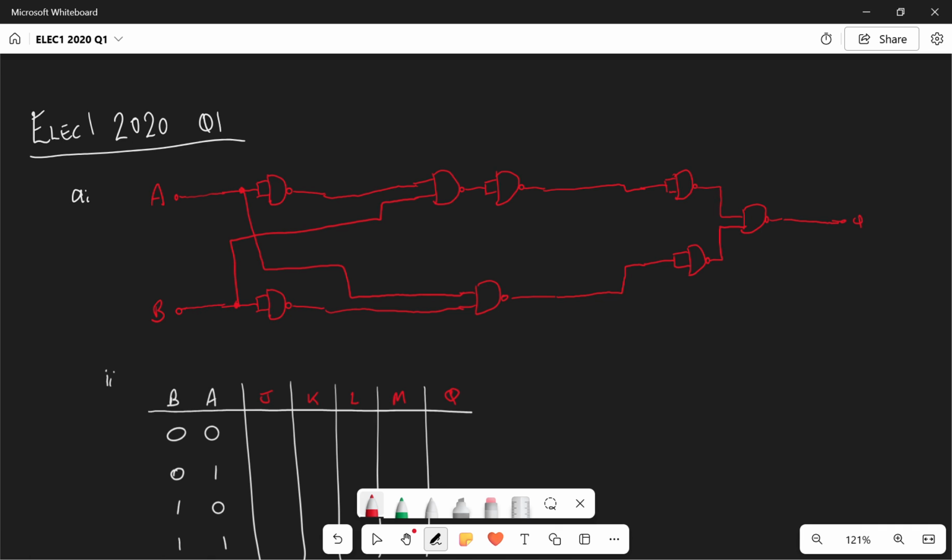Okay, now it's trying to recognize those redundant gates, and we're looking for pairs which are one after the other in the same line. They've got to be consecutive, and there's only one pair where you've got NOT gates, so these NAND gates where they've got 2 inputs which are attached together, which are one after the other, and they're at the top here.